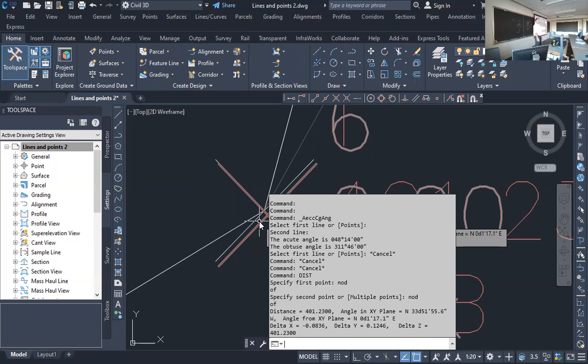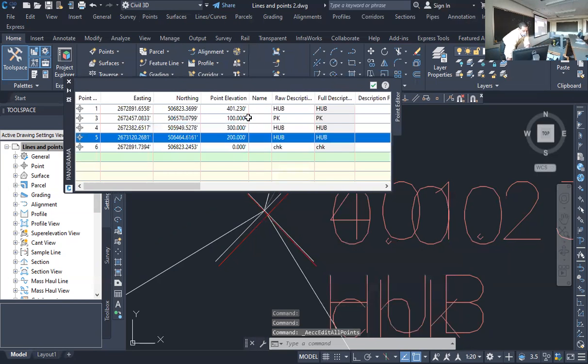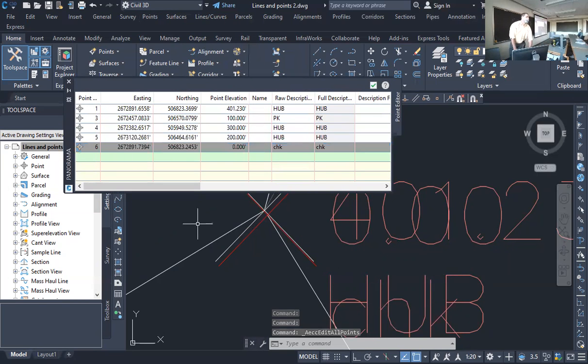Oh, snap. Did I go around and set my elevation on my closing point? No. Point list. Points. List points. See how I just kind of arbitrarily set an elevation of 100? You're going to have to go in after you've calculated your verticals, because you're going to have to do that with trig. And okay, am I going uphill, downhill? Everybody knows how to do that. We went over it. Right? And you're going to plug in your elevations. Then you can get it.